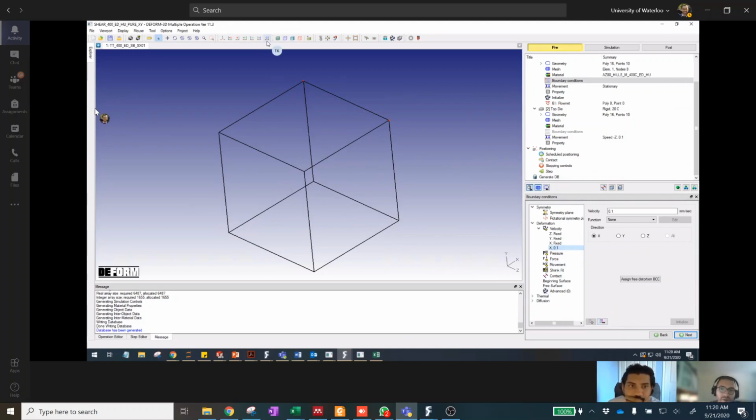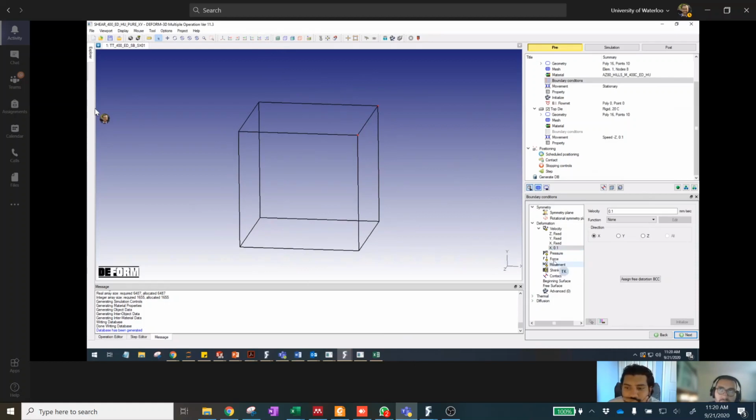This is relevant for forging because you're viewing the forging die as this radically strong thing that's just crashing into the deformable shape, the billet. It's rigid and you're imposing a velocity. But in reality, if you program the force curve into it, that would be more realistic. Instead of doing displacement control and monitoring the force, you're doing force control and monitoring the stroke. Anyways, try forces and see what happens.